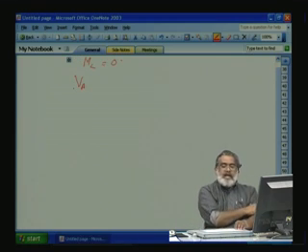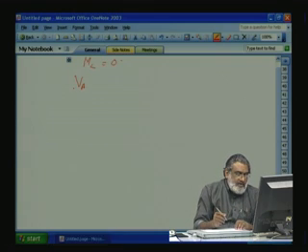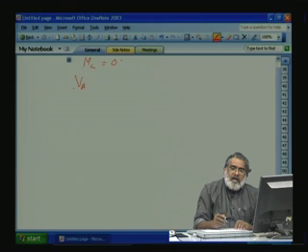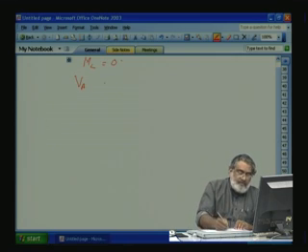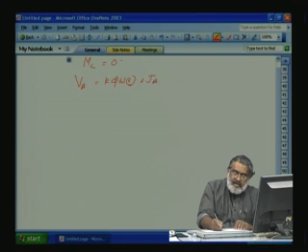Okay, and let us also assume we are giving the full current, controlling the current, so that it is always giving the maximum torque to accelerate. So, VA is equal to K phi, back EMF, a function of omega t, plus IA R.